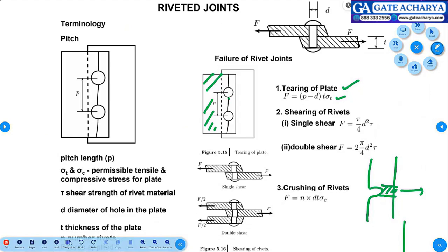Right? And all the theories of failure, if you take that terminology, okay, the expression or the equation, either square term or product will be present. Okay, so if I use sigma 1 is equal to minus 3 and sigma 2 is equal to minus 3, when you multiply, the minus sign will get removed off. When you square also, minus term will get removed off. So static theory will never capture the dynamic variation.